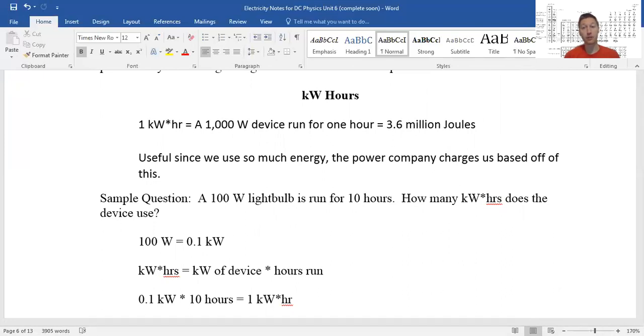And if you think about a typical light bulb, if you have a 60-watt light bulb, that means every single second that light bulb uses 60 joules of energy. You leave the thing on for a minute, that's 60 times 60, that's 3,600 joules. That's probably on more than a minute. And so you can see that the number will get really large. Your utility bill wouldn't make any sense to you if every single time you got the bill, you're like, wow, I used like 100 billion joules of energy. It'd be a really huge number and people wouldn't know what's going on.